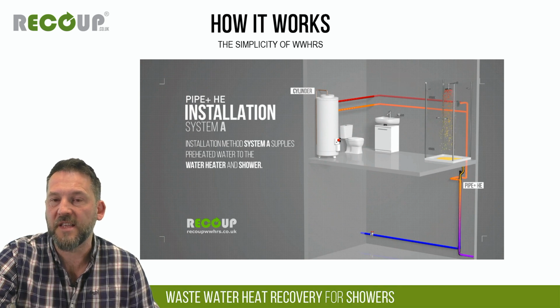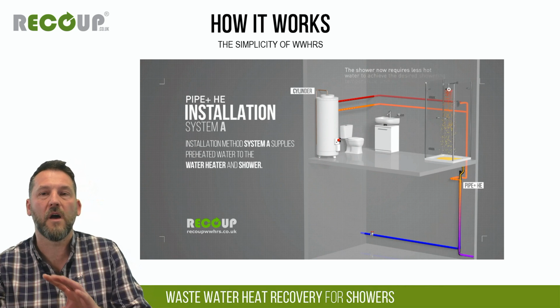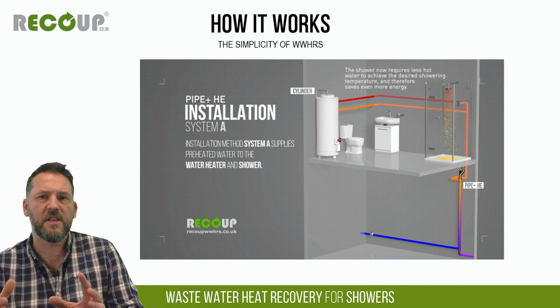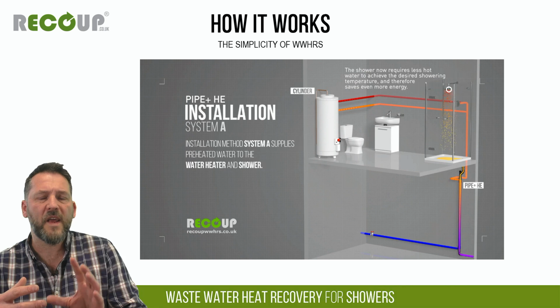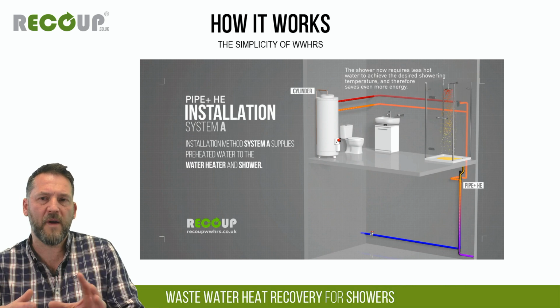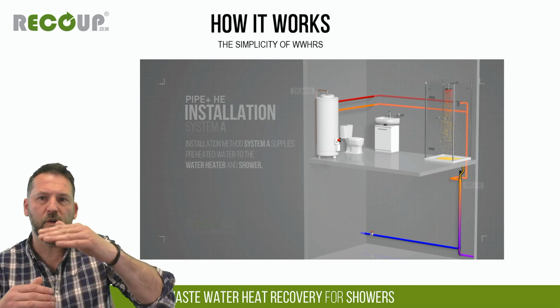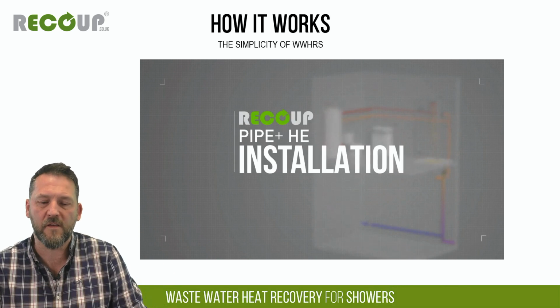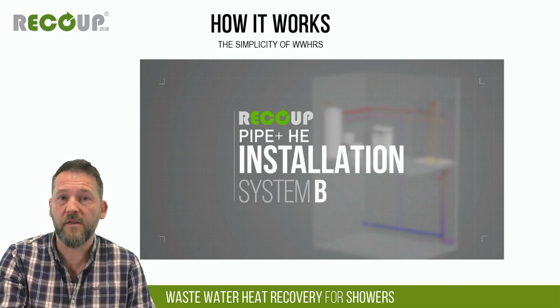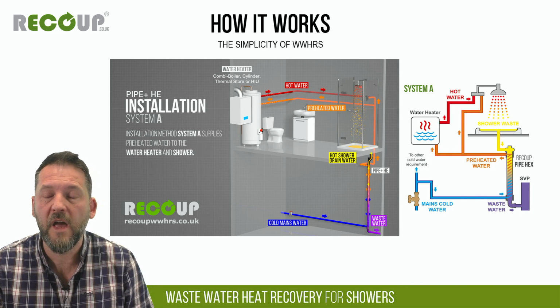and is preheated. So in this instance, at standard sort of 9 to 11 litre per minute shower flow rates, we'd expect incoming cold water at about 10 or 12 degrees to be preheated up to about 25 or 28 degrees. So it's a big free temperature uplift from that outgoing waste. And that's the basic premise of all wastewater heat recovery.